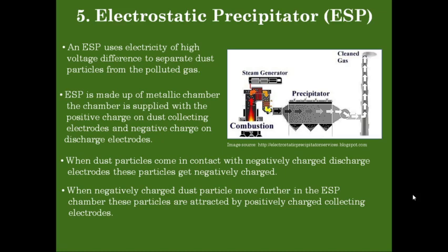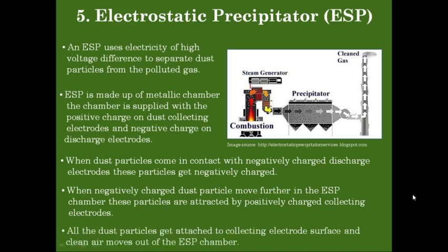attracted towards the positively charged collecting electrode, and these dust particles will get stuck to the surface of these positively charged collecting electrodes. In this way all the dust particles will get attached to the collecting electrode surface, and the clean air will move out of the ESP chamber.